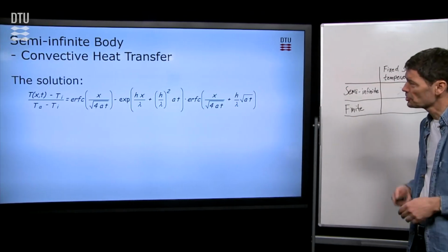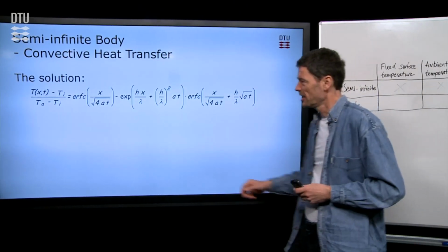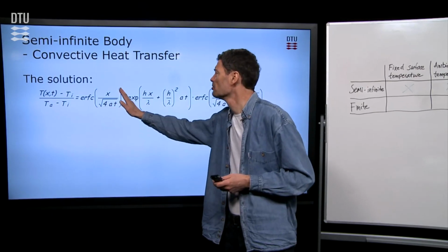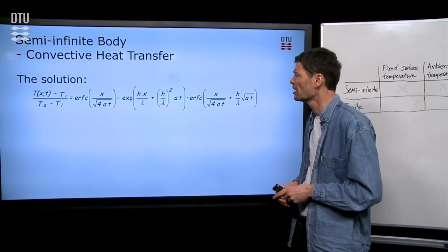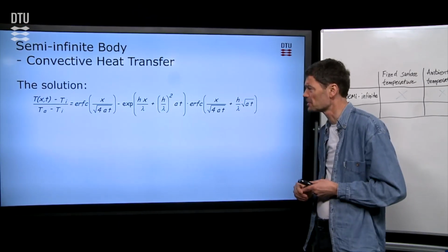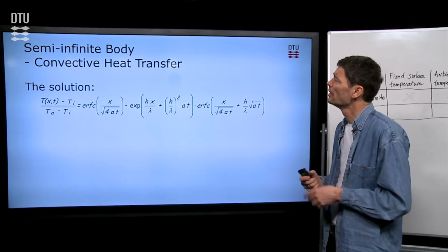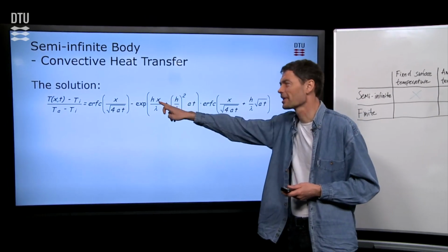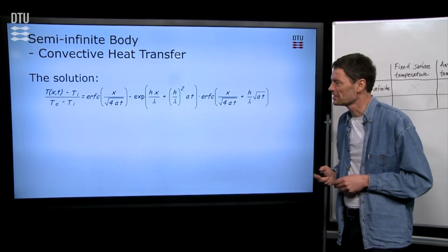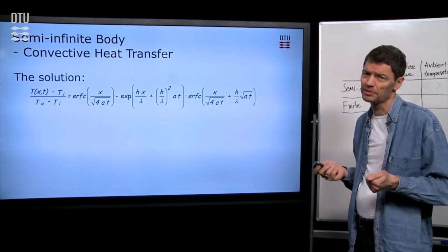Okay, so we have an equation. Again, you have to identify it. It starts the same as we had before with the complementary error function, also the same argument, but then we have to subtract a little bit because the heat flow is slower since it has first to come to the surface of the material. And that looks a little bit more involved mathematically, you might say. So we should insert, again, the location X, and this is time T that fits in this equation here. But it's a mathematical equation. You can just solve it.